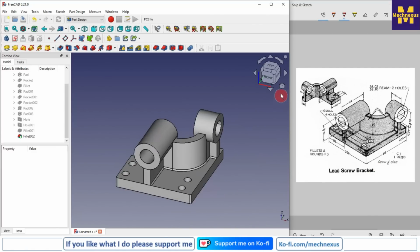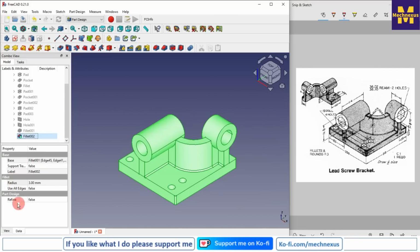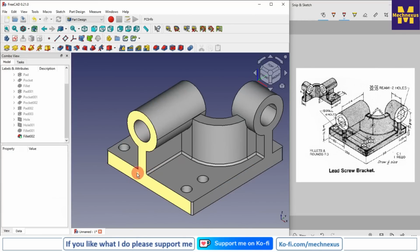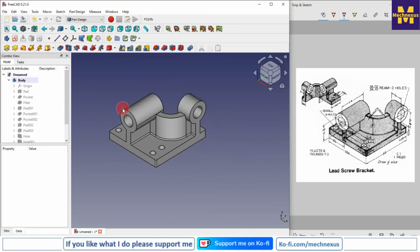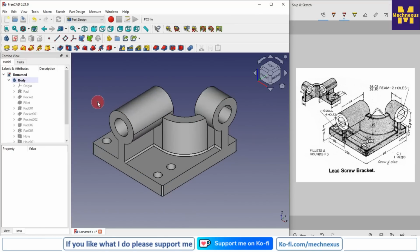And here we will refine the features. Select this last feature, and here in Part Design, refine is false. Click on true. So you can see that edges got merged like our part. So this is how we have successfully converted this lead screw bracket into the 3D model with the help of the Part Design workbench. So this is all about this tutorial.